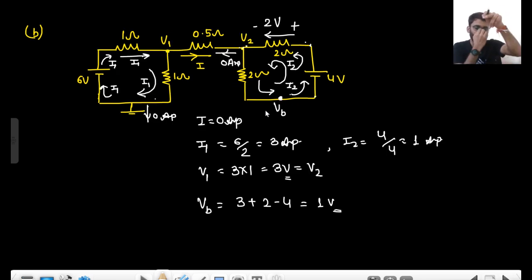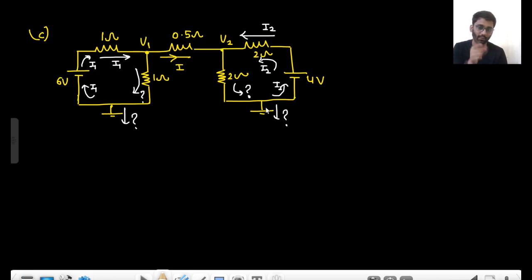So the complete current was flowing in this loop. So you could tell that there will be zero current in this resistance, in the 0.5 ohm resistance. But here you can see that this is not a complete loop. There is a ground as well, because both of these nodes are equal. So whatever current is going here, the same current will be going into this. So the addition of this current plus this current will be equal to I1 now. So ground will also have some current. Okay. Ground doesn't have zero current. Ground takes the current. Okay.